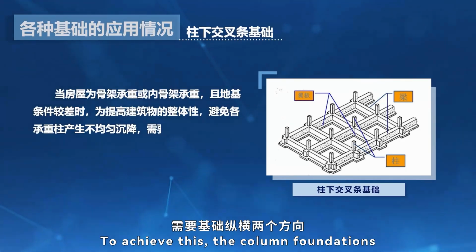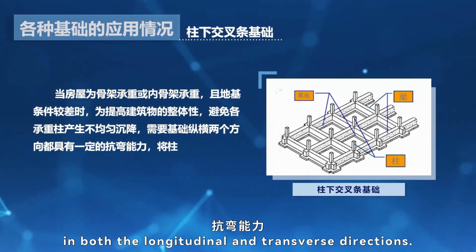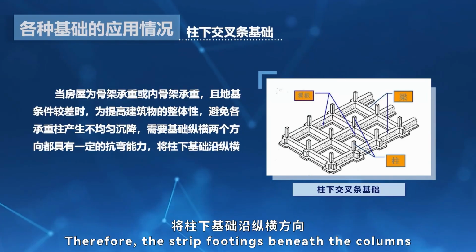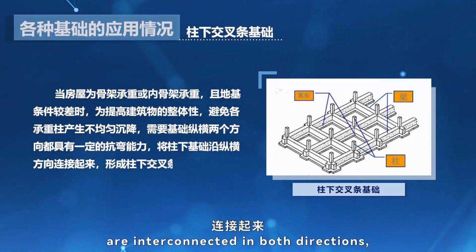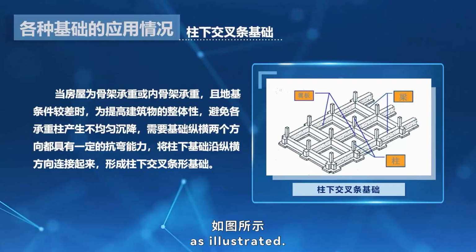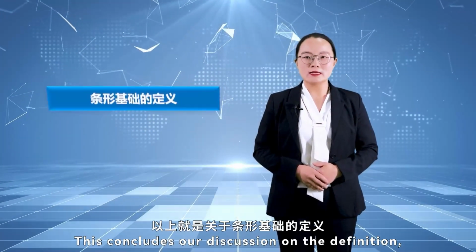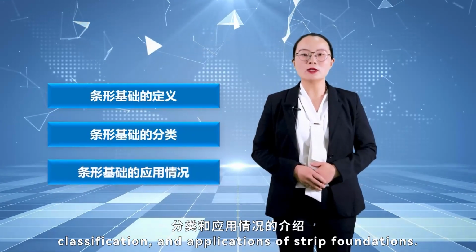To achieve this, the column foundations must possess sufficient flexural capacity in both the longitudinal and transverse directions. Therefore, the strip footings beneath the columns are interconnected in both directions, forming an intersecting strip foundation under columns, as illustrated. This concludes our discussion on the definition, classification, and applications of strip foundations.